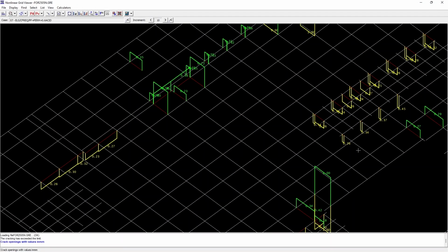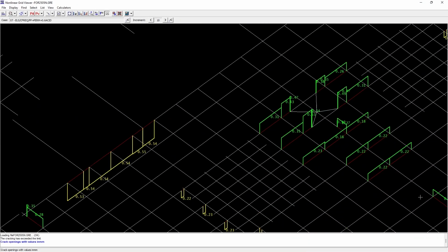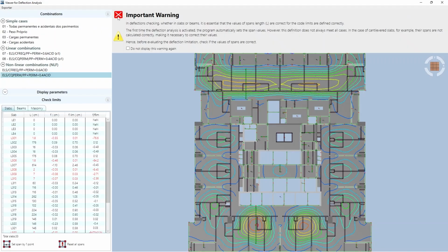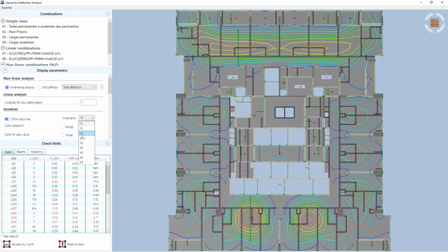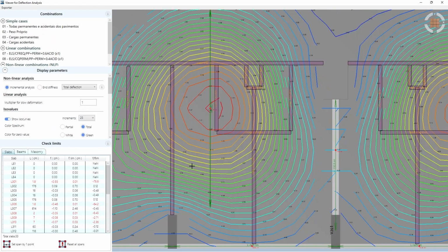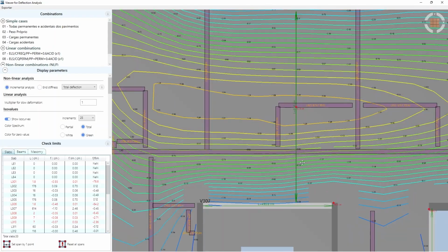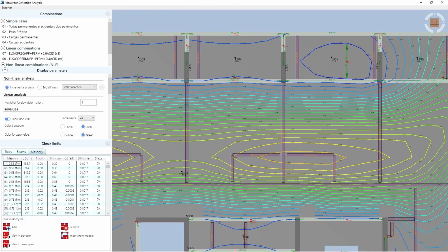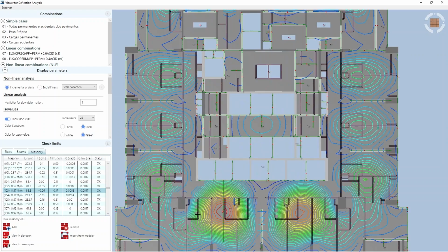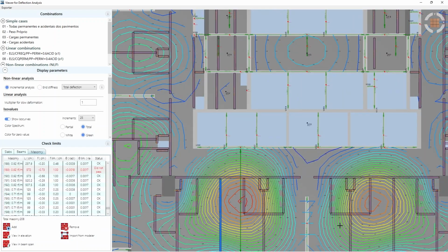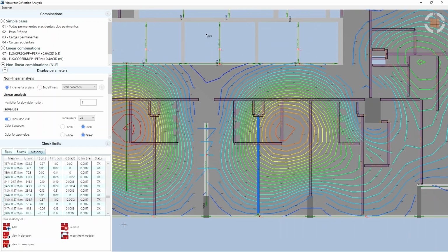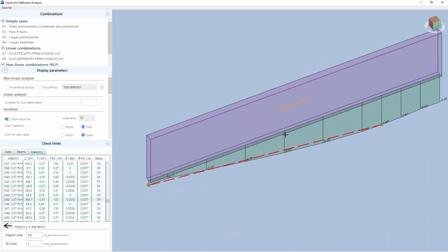Deflection and concrete crack width evaluations in slabs can be performed using an approximate linear analysis or a refined nonlinear model based on moment curvature relationships, accounting for concrete cracking, reinforcement, and time-dependent deflection. It is even possible to calculate the concrete cracking after masonry construction.